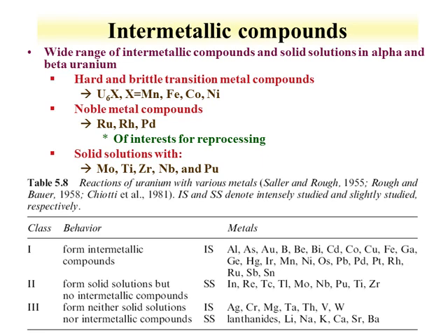Uranium alloys well with molybdenum, niobium, zirconium, and titanium. Similar to the solid solutions, the metals can also form different compounds. The alloys, as we've already talked about, are where the metals form fundamentally solid solutions, but the metal ions are just replacing each other. Intermetallic compounds can also form, and these are compounds that have specific stoichiometries. So, for instance, uranium with manganese, iron, cobalt, nickel, that composition in stainless steel, can form a U6X compound.